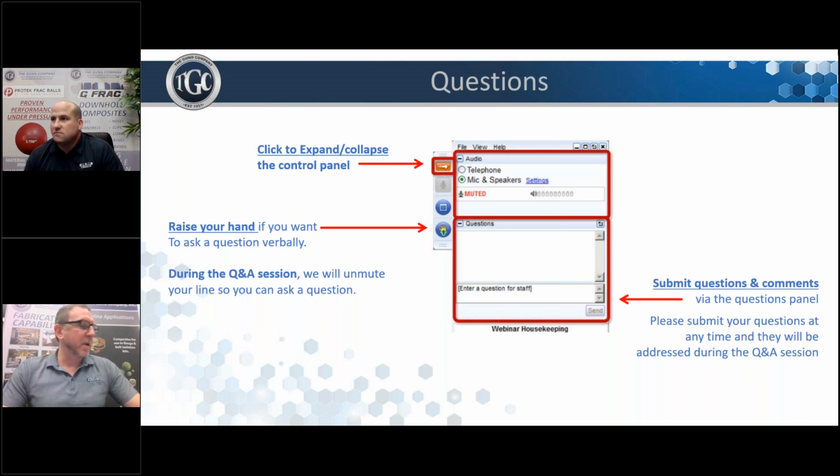Convolute is limited by how wide a fabric you can weave. You can get some wide fabrics, and then you have to saturate that fabric with resin. But typically, convolute tubes are limited to about 50 inches wide.